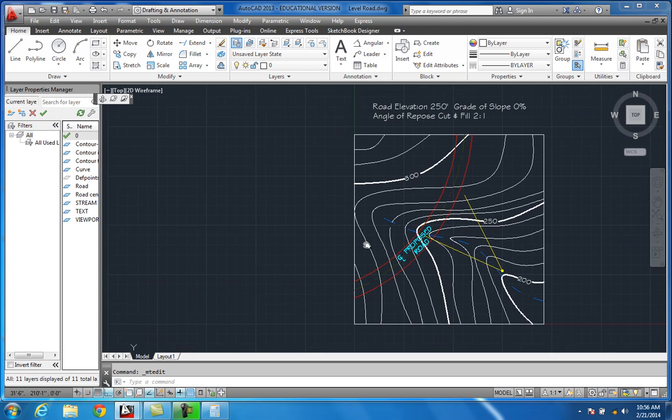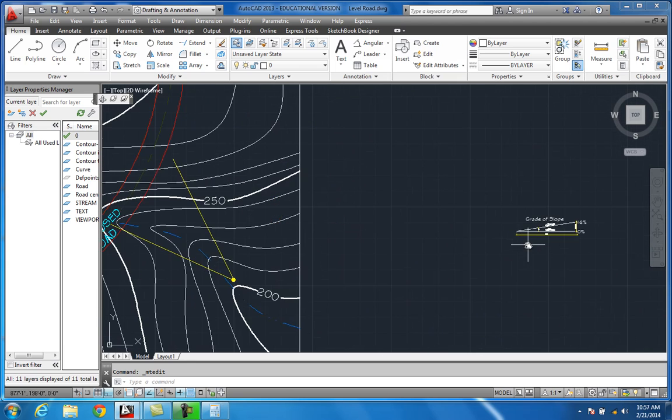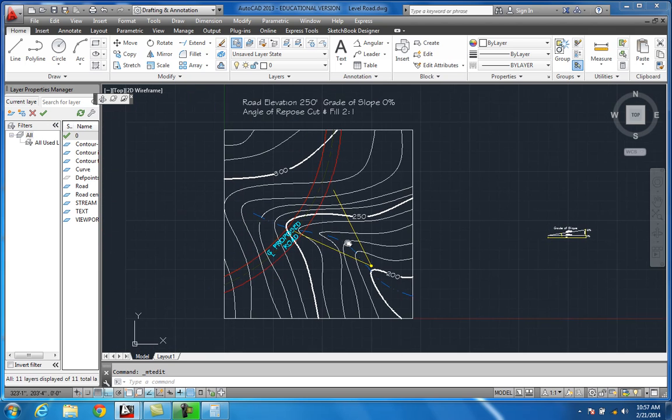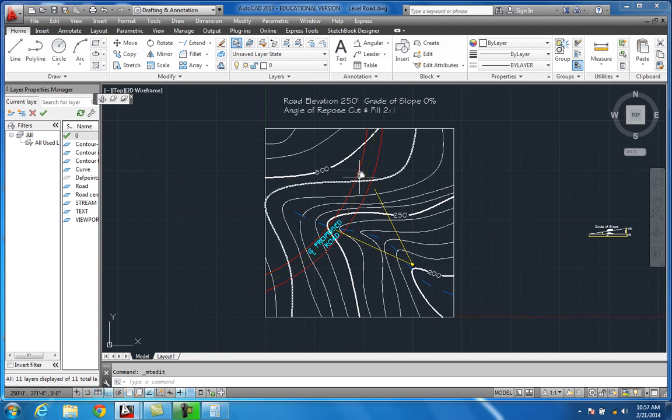All right. Now, we have gotten grade of slope figured out. We learned how to calculate the grade of a slope. Now we're going to come over here and we're going to do a little cut and fill. Okay, whenever the state comes in and they build a new road, in this area they're going to have a lot of hills. Anywhere you're at, there's no perfectly level ground, so you're going to have to cut some areas. You're going to have to fill some areas to get the road at an appropriate grade.